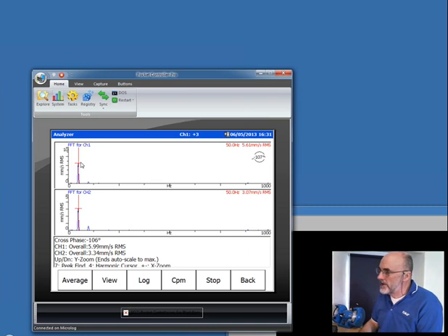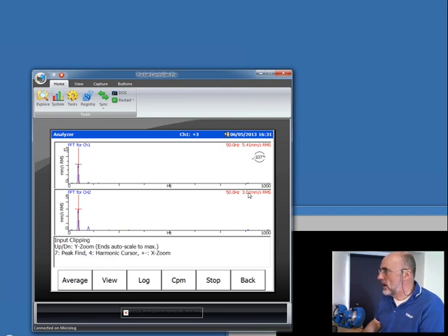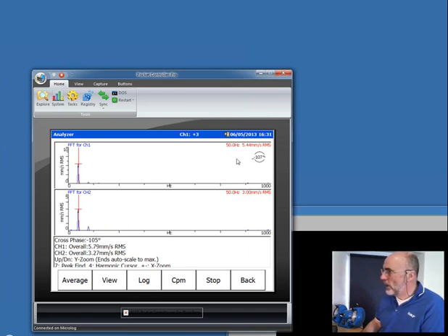So now the cursor has hopped onto the running speed, and I can see in this case we've got a reading of, where are we? 5.48 millimeters per second on the vertical and 3.3 millimeters per second on the horizontal. So 5.4 of that 5.8 is coming out at the running speed. So the bulk of the vibration is at the running speed. More evidence that you've got unbalance.